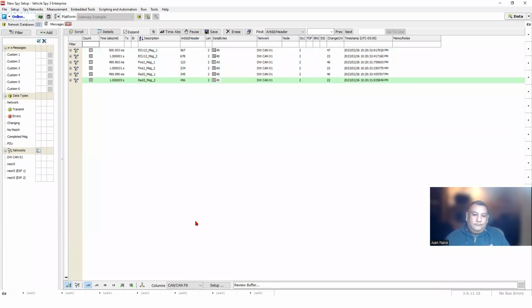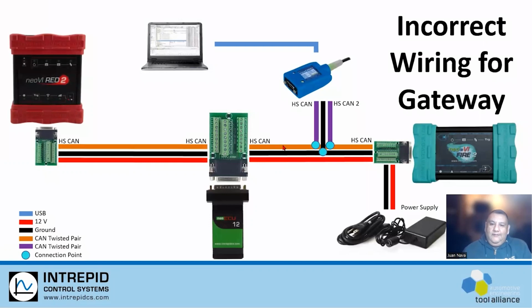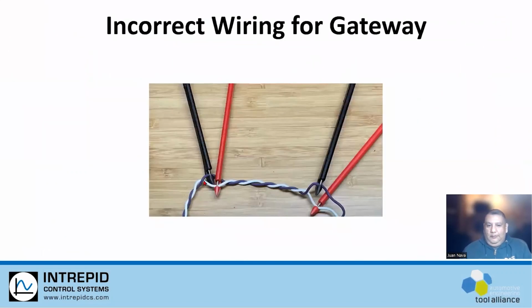I'm showing this slide here because I've seen several users do it this way, where they take 2 CAN buses from a device, and then they plug it in. It would be the equivalent of doing this on the same line, and that just doesn't work. I understand that everybody's an electrical engineer, and I work with some that are mechanical engineers, so it really doesn't matter the background. But when we do this, the electricity doesn't stop here, go to our device, and then jump back here. Electricity is going to flow in all these directions. So this isn't going to work.